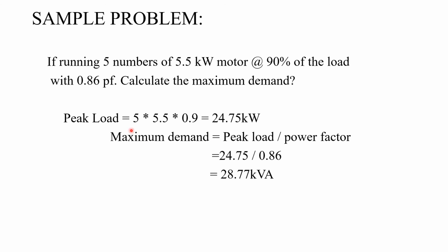And based on this we can solve a problem. If running 5 numbers of 5.5 kilowatt motors at 90% of the load with 0.86 power factor, then calculate the maximum demand. So we need to calculate the maximum demand, and these data are given here.